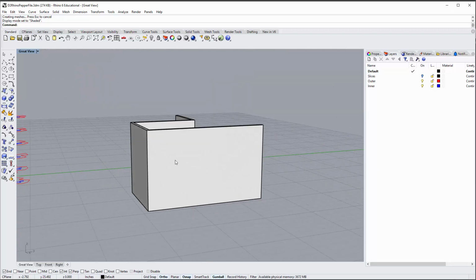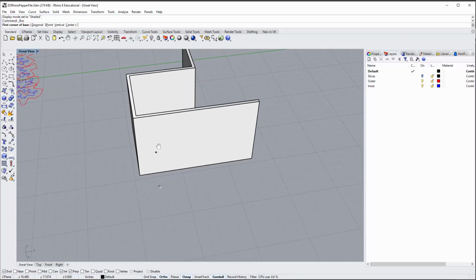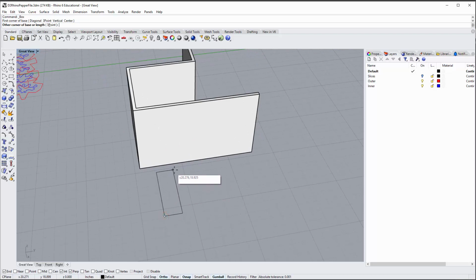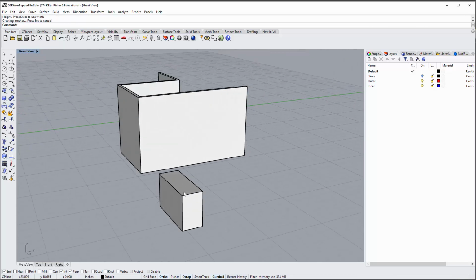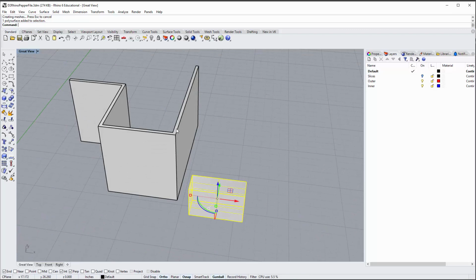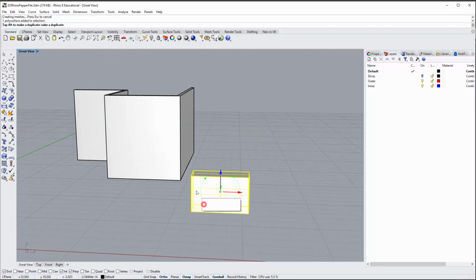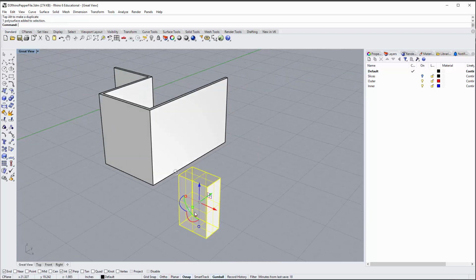These are walls, not dissimilar to the walls that you will see in the Miller house. And let's say there's a door opening here, right? So what you can do, if you know the door dimensions, is draw this to the dimensions of the door. Let's say that's the door, okay? And we don't care about the width or the depth of it as long as it's larger than the wall section, right?